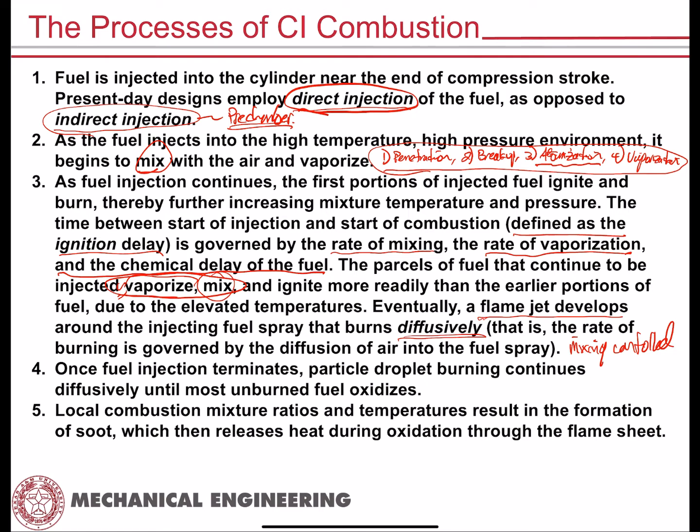Okay, once fuel injection terminates, right, then there's a third type of burning, which we call particle droplet burning. That'll continue, and that does so diffusively until most of the fuel is burned and oxidized. But of course, you will have local combustion mixture ratios and temperatures that will pyrolyze the fuel, just as we've talked about already earlier.